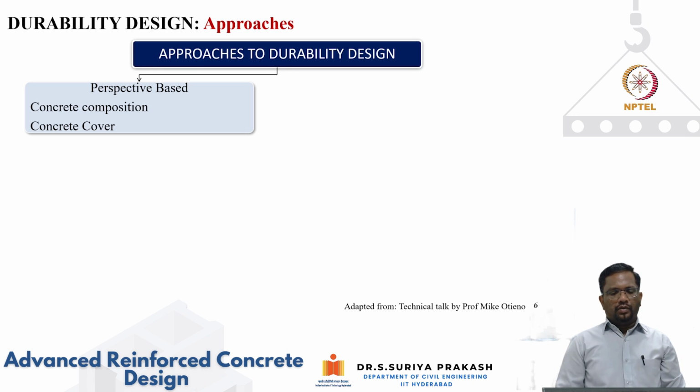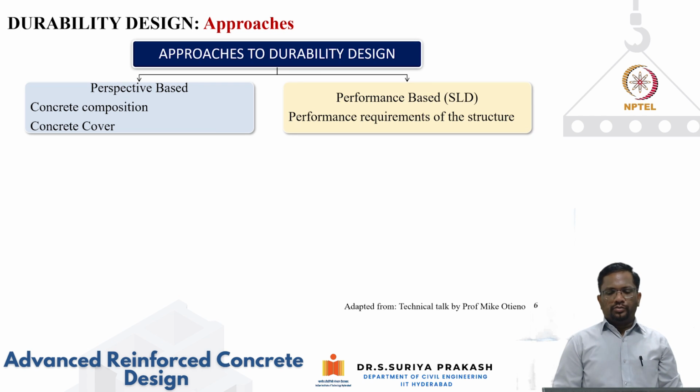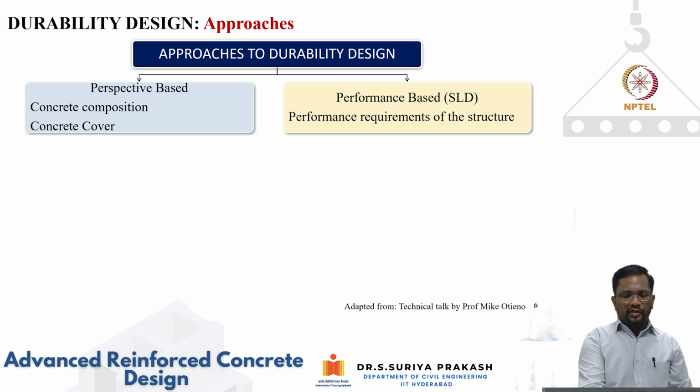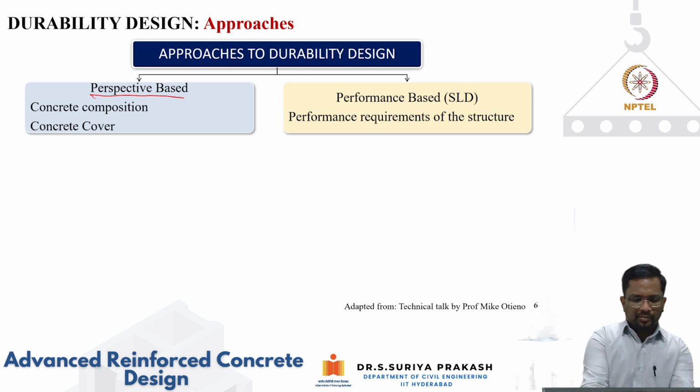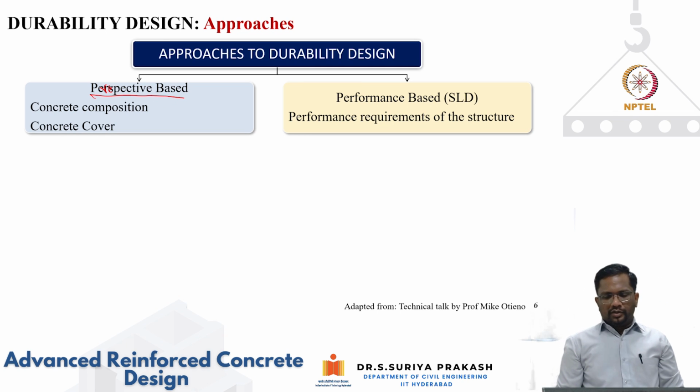If you follow the provisions given in the code broadly in terms of concrete composition, what your maximum water cement ratio should be, what your minimum cement content should be, and if you satisfy the cover requirements, you are assumed to have satisfied the durability design requirements. That is what is prevalent now, which is prescriptive based.